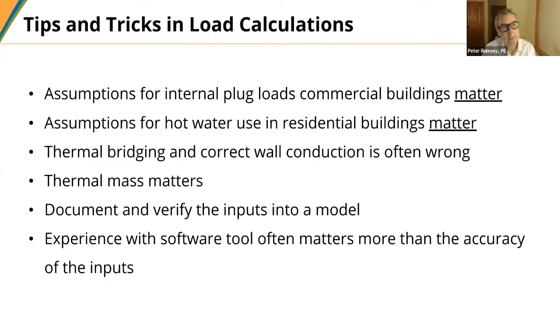Thermal mass matters. So we do have a lot of buildings in India that are made with concrete. They're concrete structural systems. There's a lot of concrete in the building, meaning that there's a flywheel effect in the building. And so as the day warms up and people come into the building, sun is shining into the building, that thermal mass will absorb some of the heat. And so the cooling load is a little bit lower because of that. And sometimes it can be a 25% factor. So in a load calculation, there are simple ways to take into account the thermal mass.